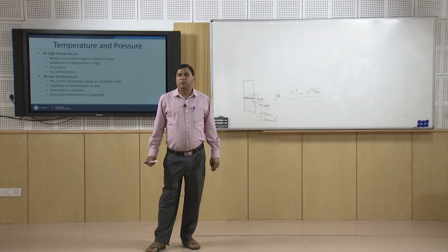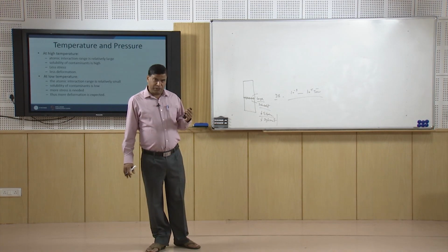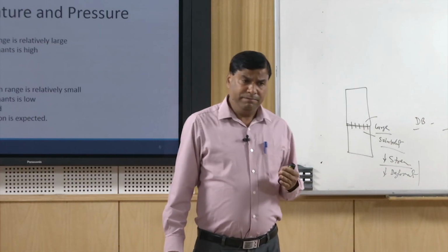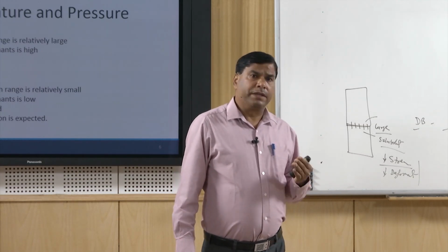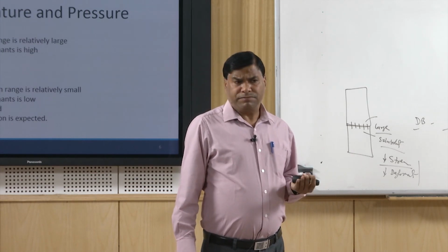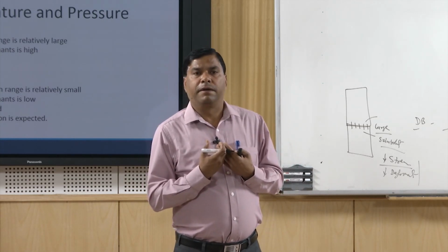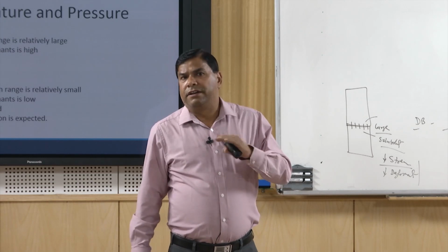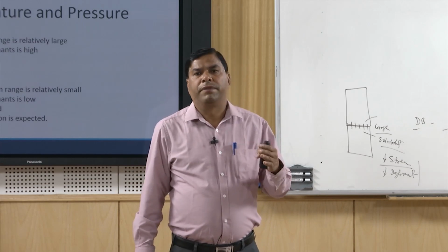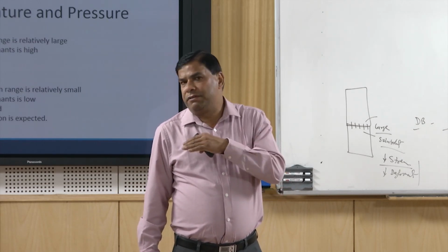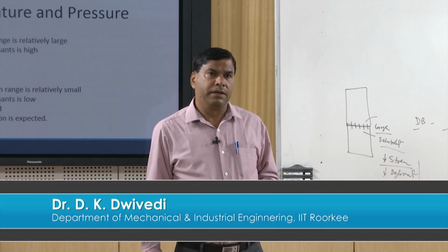So, now I will conclude this presentation here. In this presentation, I have talked about the fundamental principles based on which solid state joining techniques work, and there are basically two approaches. One is interfacial deformation, so that the surfaces can come close enough to reach the atomic bonding range, and another is diffusion, wherein diffusion across the interface helps to form grain boundaries and achieve metallic continuity through diffusion during the process.